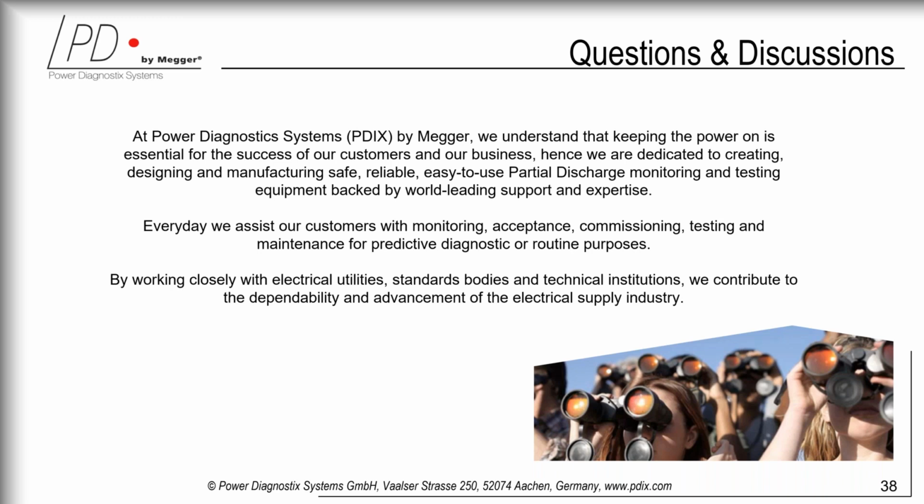It's the first indication. If we are measuring in picocoulombs, according to the IEC 60270 calibration procedures, below 1 megahertz. If we go into higher frequency and we measure in millivolt, then we do not have the comparison with the factory test. So here we have to set a level according to our experience, let's say, put it this way.